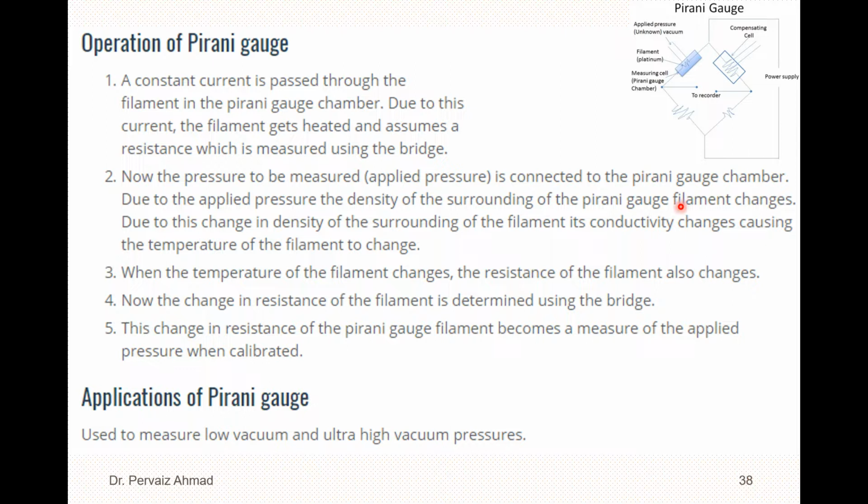Due to this change in density of the surrounding of the filament, conductivity changes, causing the temperature of the filament to change. Then, when the temperature of the filament changes, the resistance of the filament also changes, since resistance is related to temperature.